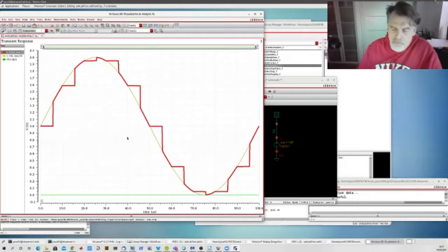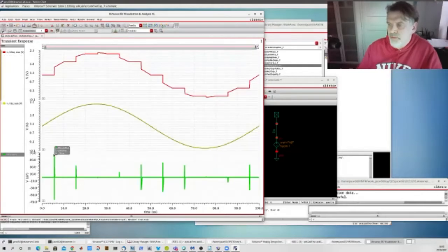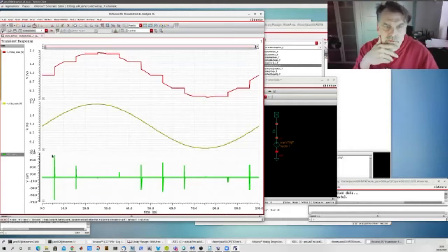Okay, so we can also look at the current. I plotted the input current. It's not super interesting perhaps, but charging a cap with very low resistance is more or less instantaneous. If I assume that the switch has a very low on resistance, it will charge with a very, very high frequency. So in the labs, you will test what happens if the switch resistance is much higher, so you get a delay for the signal to go from input to output.